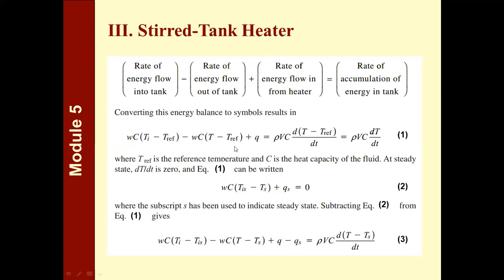If you're working in SI units, this is 0. If you're working in English units, this is 32, just like the way you do it in your unit ops. So the reference temperature is 0 unless the problem says to use a reference temperature of 25. But if the problem is silent about it, if it's SI, your reference temperature is 0, and 32 for English.